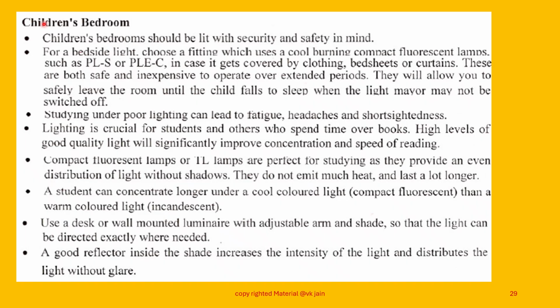Friends, children's bedroom. Children's bedrooms should be lit with security and safety in mind. For a bedside light, choose a fitting which uses a cool burning compact fluorescent lamp such as PLS or PLEC, in case it gets covered by clothing, bedsheets or curtains.